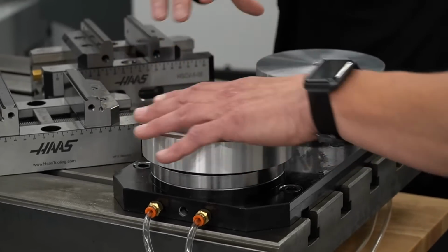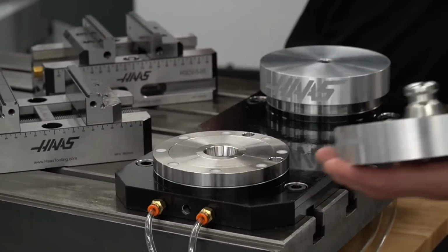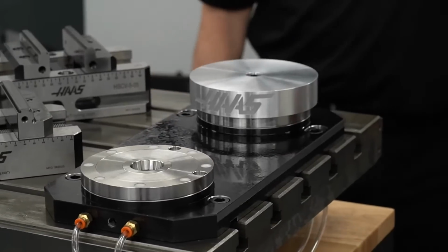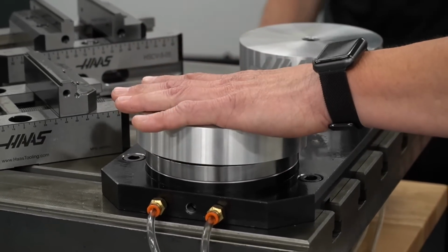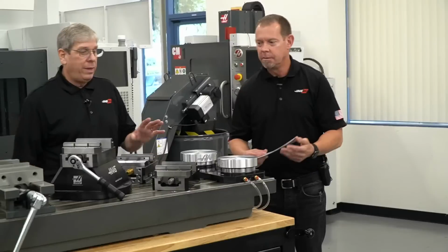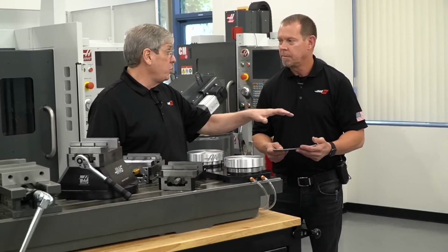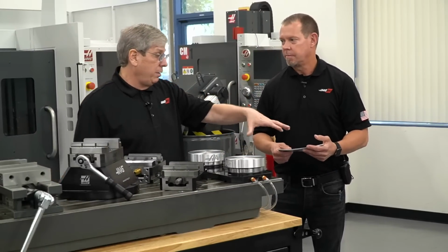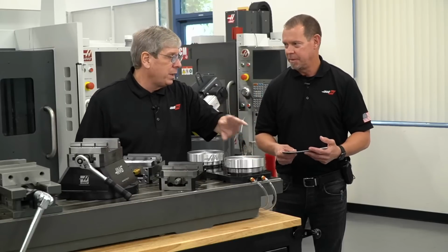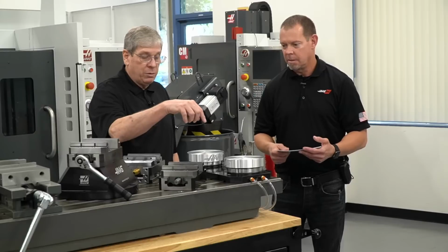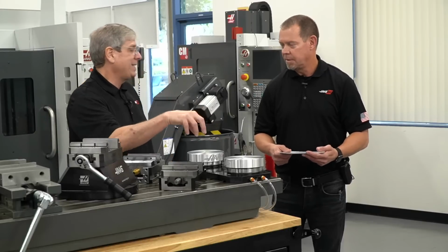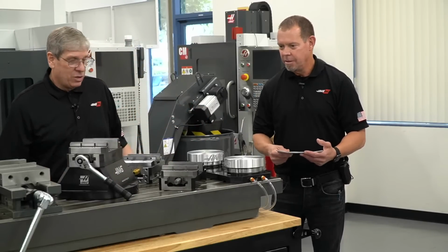Okay, let's pull this pallet off. Most people know, but just in case. So super quick, yeah, to your point, you've got a fixture to pallet, and clamping it is as simple as that. You're done. Pull that pallet off, you can take it to another machine, and you don't have to indicate it in, you don't have to pick up the zero-point if that other machine has been calibrated, or your work offset has been set to the center. To the center, yeah. Right. So excellent.